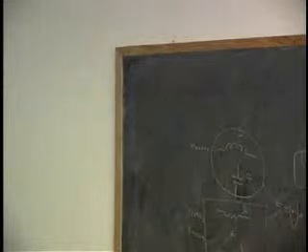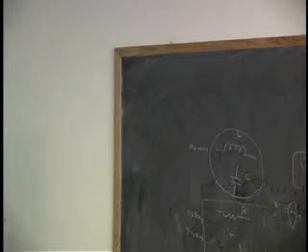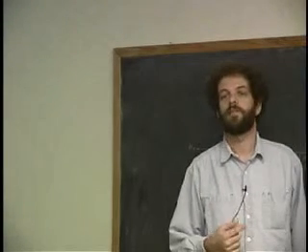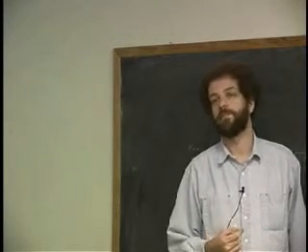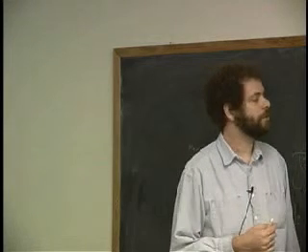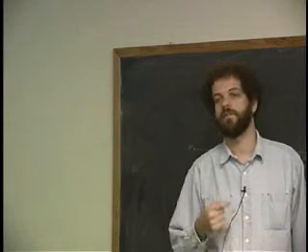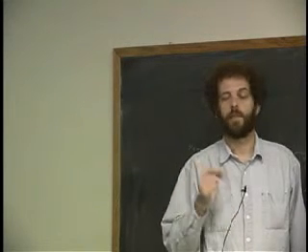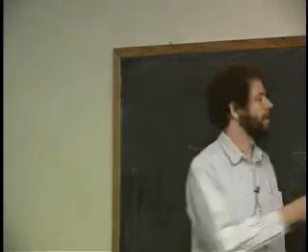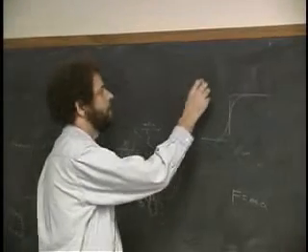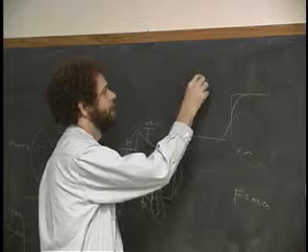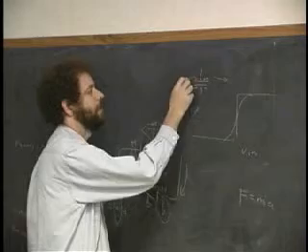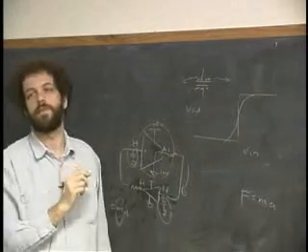So, how are inductors used, coils used? So typically the inductances on a chip are not big enough to actually make use of them for memory. And so they're typically not used. It's also the case that an inductor is a much less ideal device when you build it out of wire than a capacitor is when you do the same thing. So in a capacitor, you have to worry about the fact that you put some charge here, like we talked about the other day, and some of it will leak off because the insulation isn't perfect, okay?